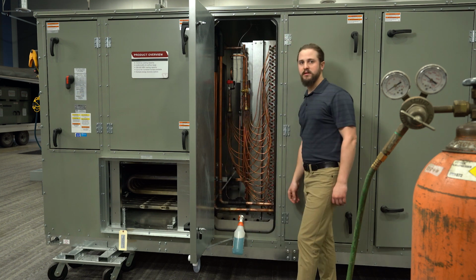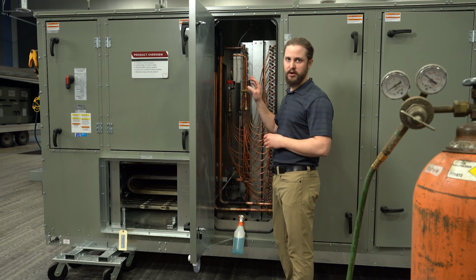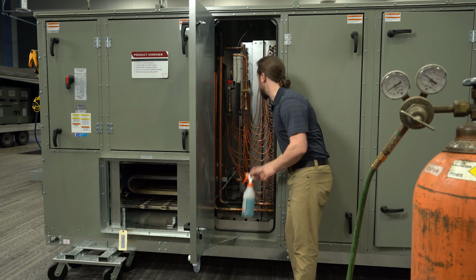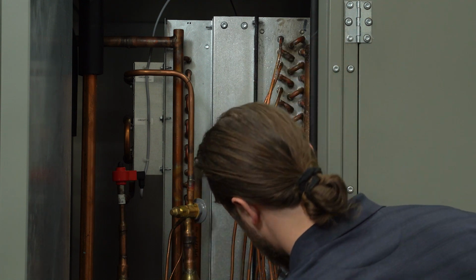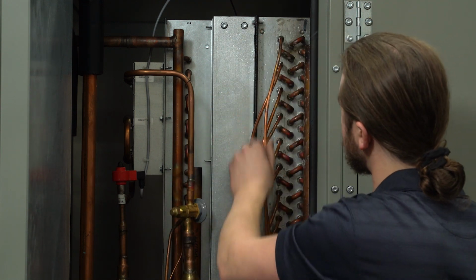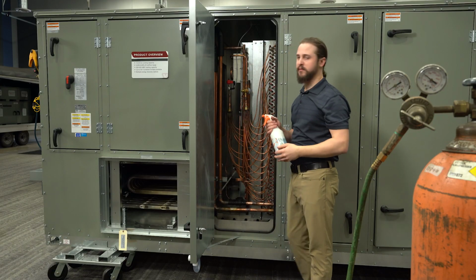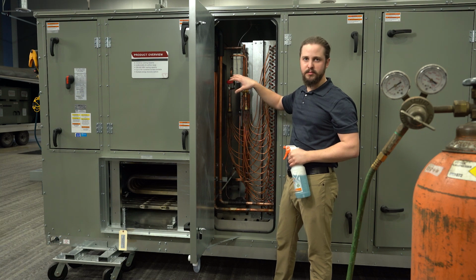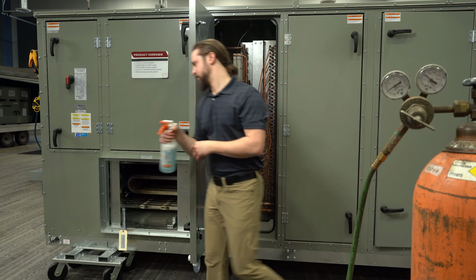All right, now that we have our leak brazed, we pressurize with 450 psi of nitrogen already. We're going to spray again here, verifying this leak has been fixed. Okay, looks like it has. For the purpose of this training, we're going to go over to the front of the cabinet and then look at some other potential leak locations, how to identify them and fix them.